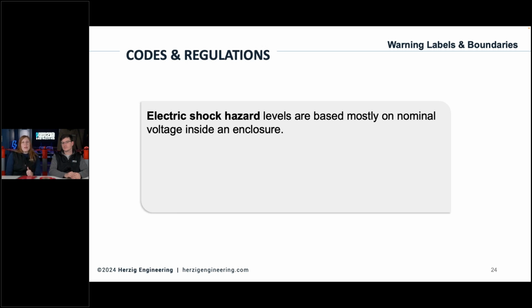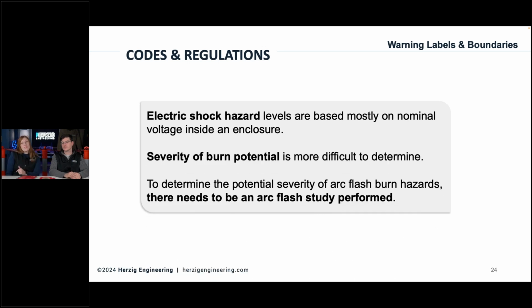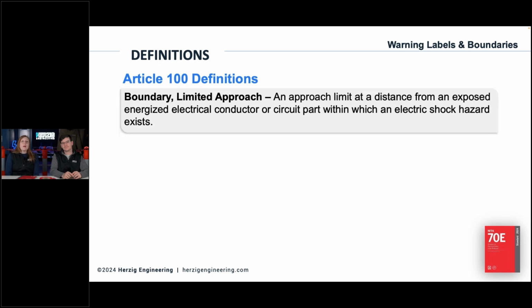You're good to go. But the arc flash hazard, the severity of burn potential, is more difficult. That's where you have to have that arc flash study performed. Otherwise, you're just guessing, and you shouldn't be guessing with people's lives. We'll talk about arc flash boundaries, and you can't get that without a study. Exactly.